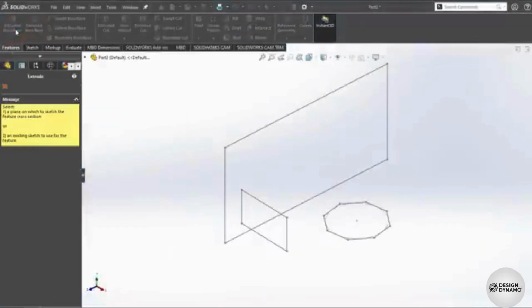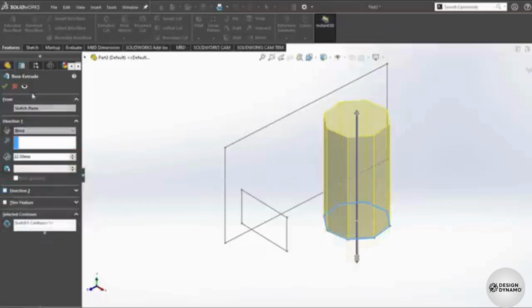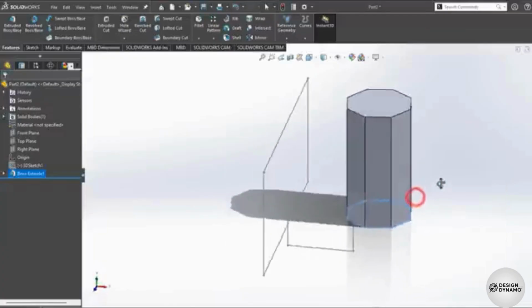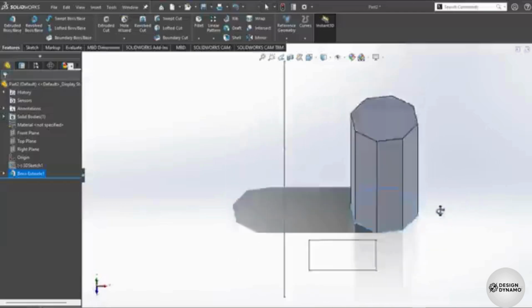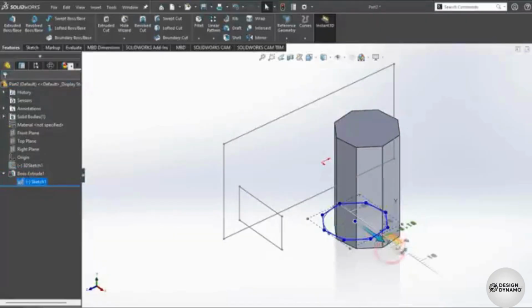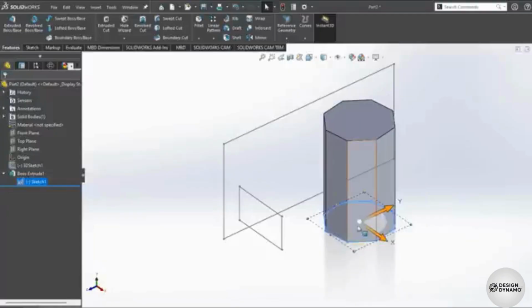Enable Extruded and select a 2D sketch entity to add extrusion to it, adjusting proper options on the left. Then right-click or use the green checkmark button to apply. The 3D feature built shows some effects, such as shadow and reflections. The 2D sketch used becomes a sub-component inside the 3D feature, but you can always edit it as seen. The 3D feature simply gets updated according to your modifications.